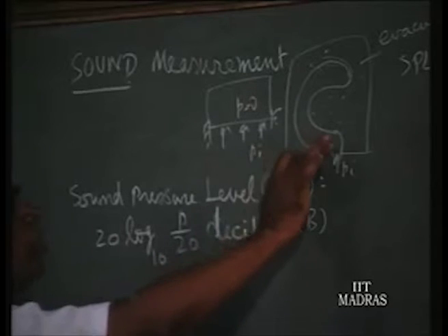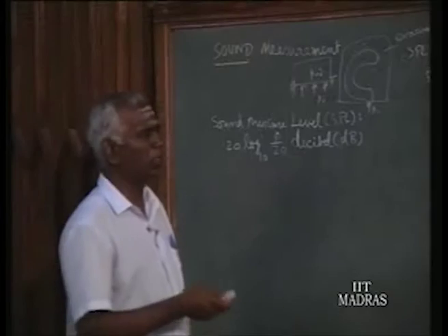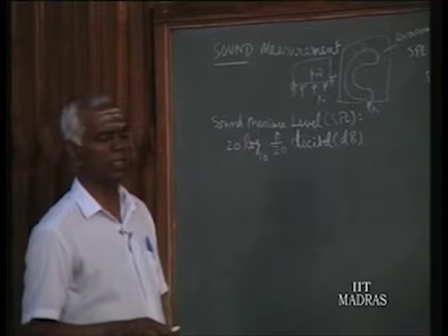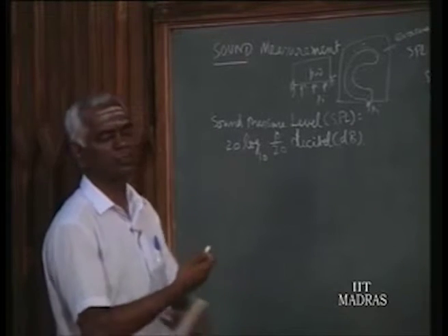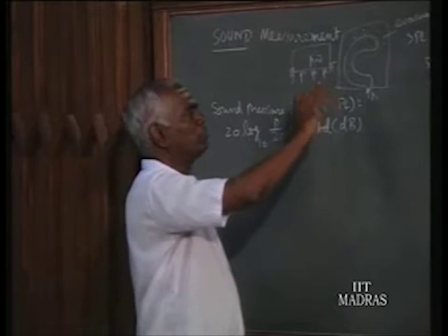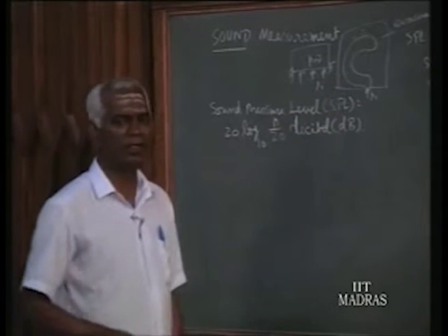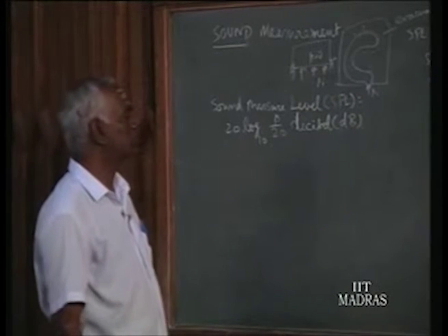So the Bourdon tube, the diaphragm or the bellows can also be used to measure vacuum of low and moderate values. Other methods we have seen in detail last class, that is McLeod gauge and viscous vacuum gauge and Pirani gauge and all other methods. Otherwise, whatever method we used for the pressure measurement we can use, provided the surrounding in which the instrument is there is evacuated and the absolute vacuum pressure is applied inside the tube. That way we can measure it.